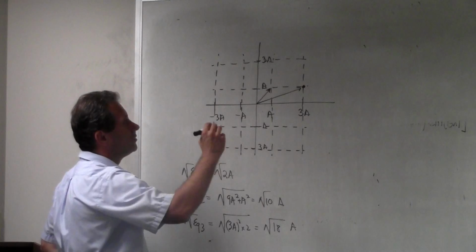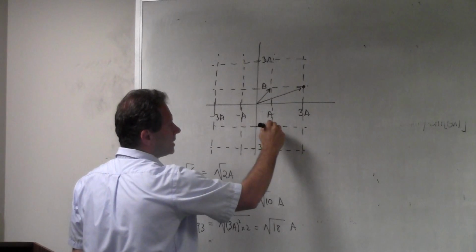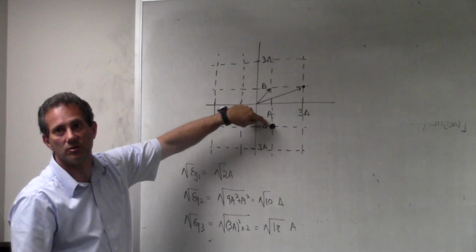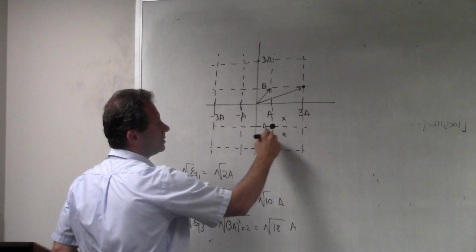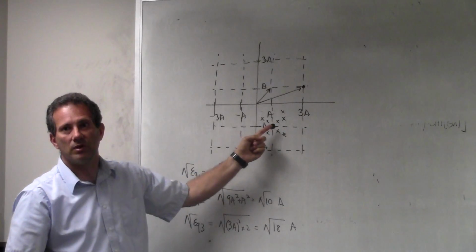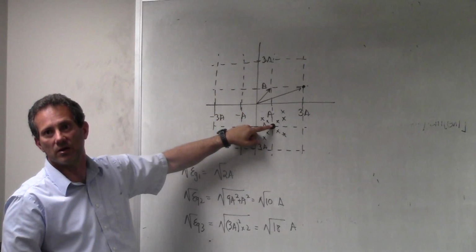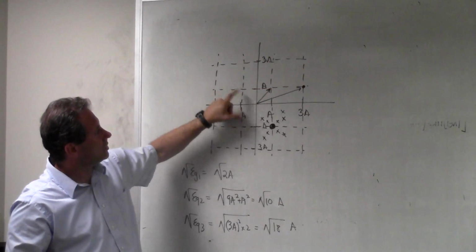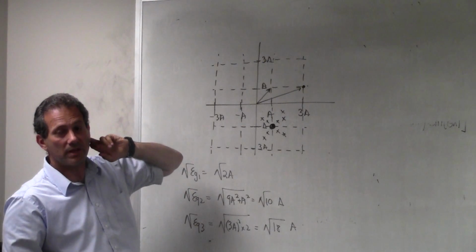To answer your question, this will come into play later when we talk about the nodes, but you can understand it with some minimum explanation here. This is the constellation point that you use. When you send a signal, what noise will do on the other side is move your constellation point somewhere in its vicinity, depending on how large the noise is. You're trying to make sure these disturbances are least likely to produce errors, and you accomplish that by making sure that in every direction your nearest symbol is approximately the same distance. So that's the design goal.